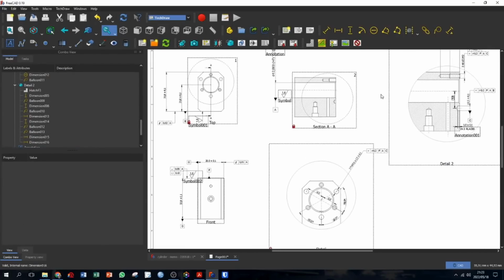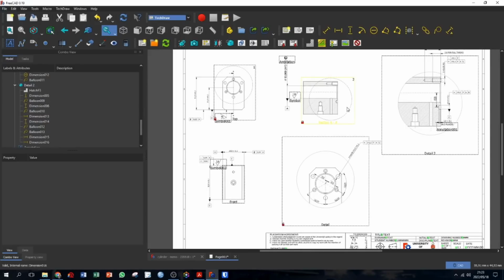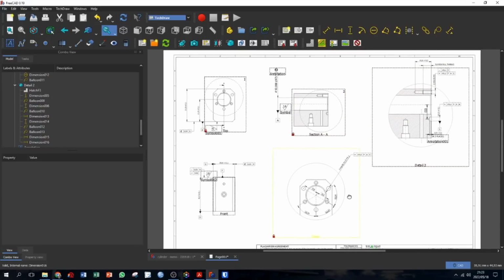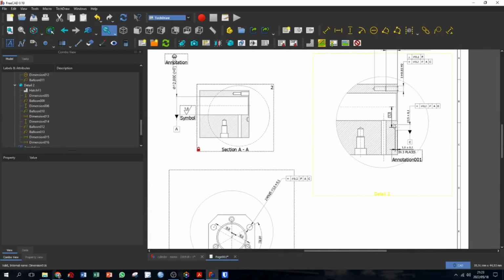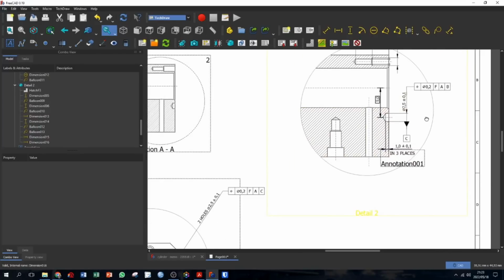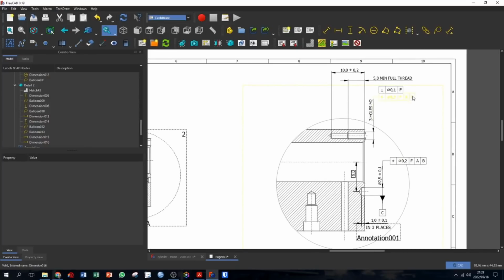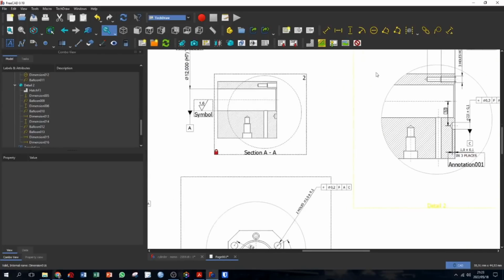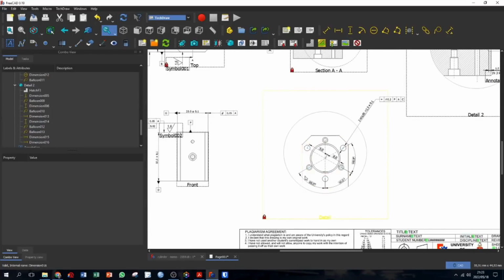Okay, the rest of the detail I'm not going to add to this tutorial. It's already a very long tutorial. So basically what I wanted to show you is how we can make use of a single hole that is positioned. We make it a datum, and then we reference the other holes relative also to that datum C. Okay, so I wanted to illustrate that methodology here.